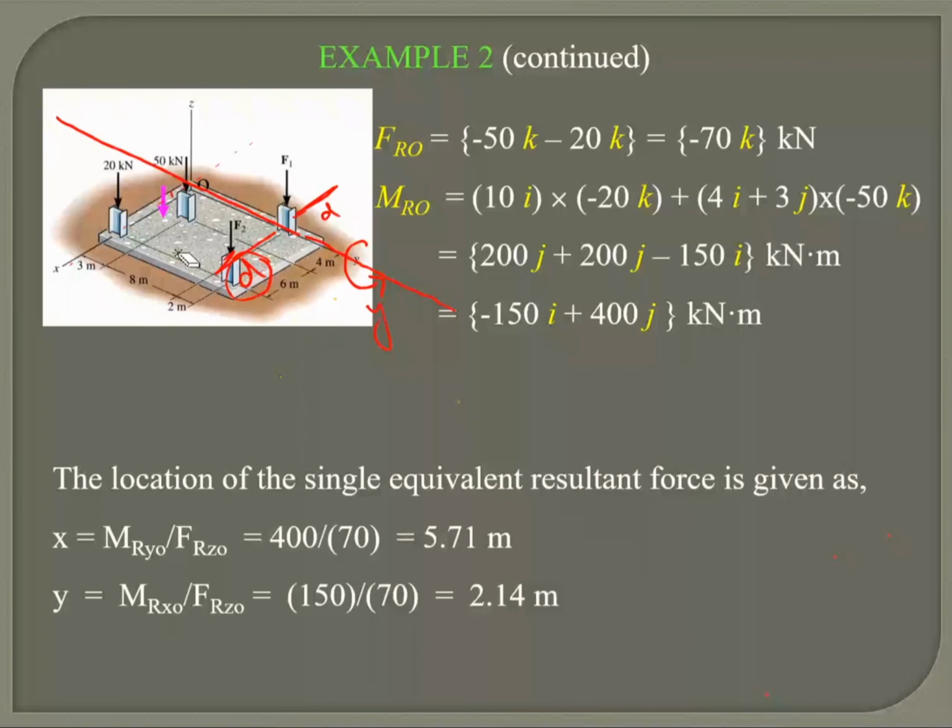If I've got a force in the vertical direction, along this line, acting up or down, will that create a turning moment at y? Yes, sir. No, it won't create turning moment at y because there's no perpendicular distance. It's along the y-axis line.